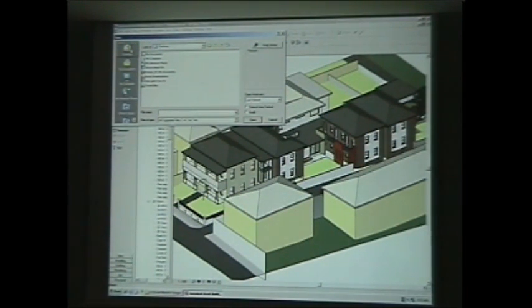Within that material definition, you can add a bump map to it, which gives it some roughness, some texture, and have a rendering that uses that in 10 minutes or less. So it is very good for that, but you're not going to print an A1 high definition image from an AccuRender rendering and have it feel real.